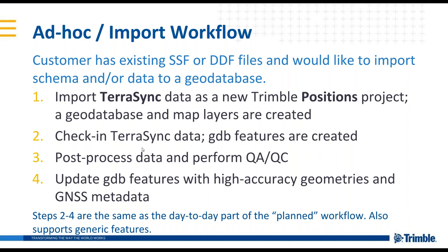So the basic workflow here is there's a separate type of project you saw there, and I'll show you in a minute, called a TerraSync import project, and this is where you're able to create a new positions project by browsing to an SSF or DDF file. What it'll do is it'll read the schema out of that SSF or DDF and create a file geodatabase and create new layers in an empty map document. You then have the ability to run through the normal check-in process. Check in the SSF, check in that data, it creates a geodatabase features, you can post-process, perform your QA/QC, and then update your geodatabase features.